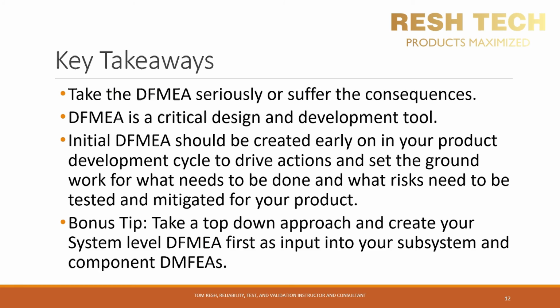I'm in a really good mood today, so here's another bonus tip. Don't work in a silo on your DFMEA. You should be communicating and working with others in your engineering group or cross-functionally to ensure that you have identified and accurately documented all failure modes and their impacts for your design, and failure modes that may impact other teams' designs as well. Hopefully you have a systems engineering team and or a reliability engineering team driving these cross-functional DFMEA activities. But if not, be proactive, don't be lazy, and you will look like a star when you produce an awesome, robust product design.